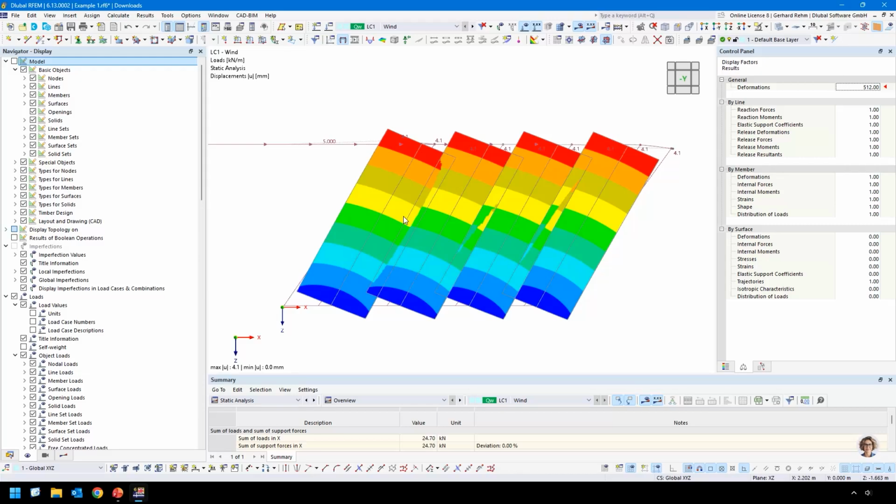And especially when we think about practical usage, we need to make sure that there is compression, or there can be compression transferred. But what about if you apply the sheathing to the walls? It must be perfectly fitted together. There should be no gap in between, which cannot be guaranteed. And that's why we use this approach. There is overlapping in the deformation, but the influence, I've checked it in an FEA submodel, the influence is nearly zero. It's not worth to talk about.